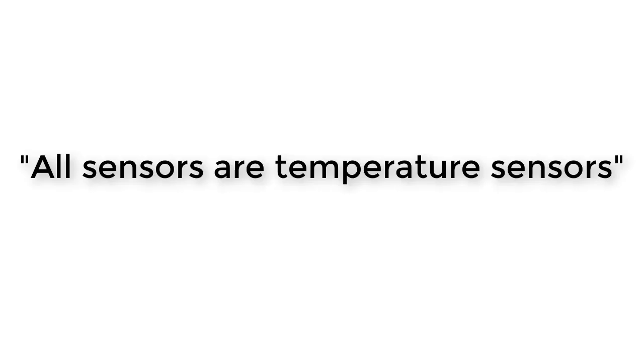There are other kinds of noise in which environmental conditions affect our sensor output. For example, there is a somewhat joking statement among sensors engineers that all sensors are temperature sensors. This means that it is very common for temperature to have an effect on the output from a sensor. Most sensor datasheets will specify the temperature conditions under which the sensor was tested. It might specify things like the sensitivity at a particular temperature. The other environmental condition that often affects our sensor output is the humidity. You have to be especially careful about this with capacitive sensors, since capacitive sensors rely on having a particular dielectric constant, which can be different when water is involved.